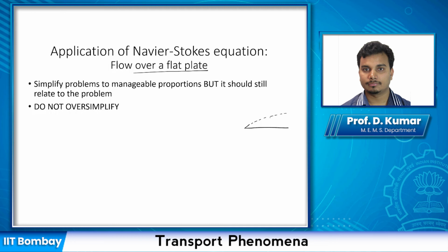Okay, so you are aware that if you have this fluid flowing over this solid plate, which is stationary, you call this velocity V infinity. And so there will be some formation of boundary layer. We know that. Because of interaction of the fluid with the solid surface, there is some friction term coming up, and then due to viscosity, this information will travel in the bulk. So you will have this boundary layer which will keep increasing along with x.